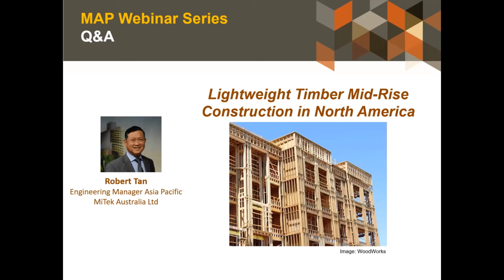Actually, I tell a lie. Something I didn't put into this presentation is the Hardy Frame over there. There's a whole lot of metal shear wall inserts that they put into timber frame buildings. I should have put that in here, but I was so focused on all timber, I forgot. But there are a number of steel shear panels that they insert between studs over there, and they're very, very high strength, very, very effective.